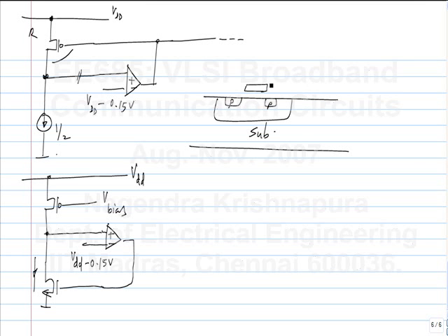So, it will have the gate capacitances from gate to the other terminals, as well as these diffusion capacitances and so on. But then if you have resistance on a polysilicon layer which is separated from the substrate, it can potentially have a smaller capacitance because it is farther away and it is not in direct contact with the substrate like the transistor is, right.